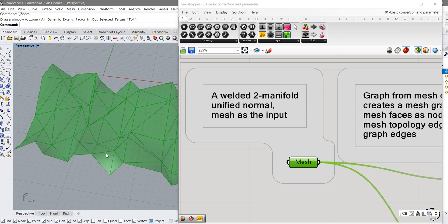First, you find the rotational angle between 4 and 1, and then you unroll the part which is connected to 1 using this edge as the pivot. Now you have flattened 4 and 1.